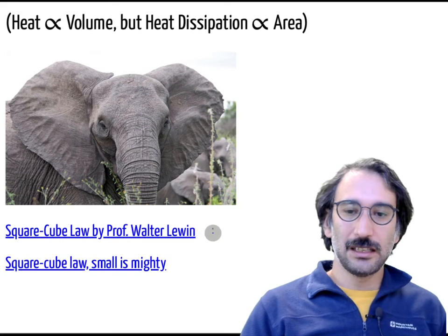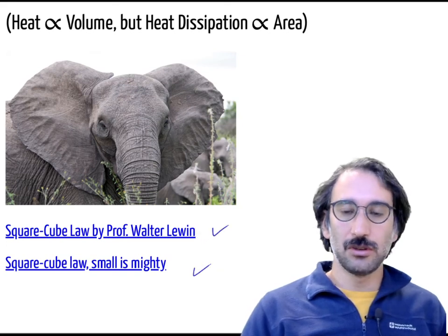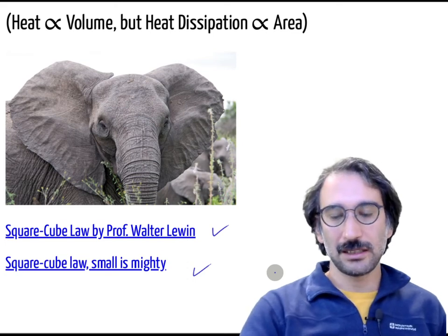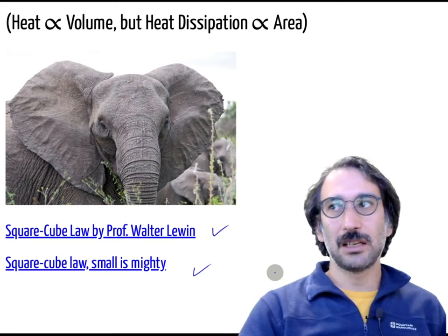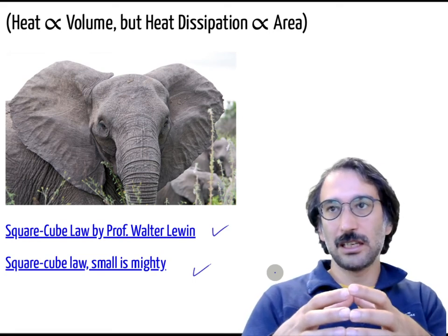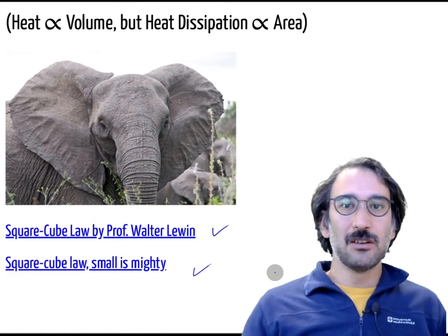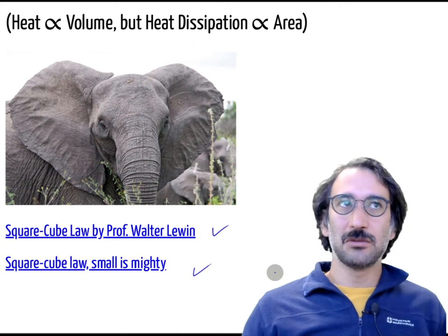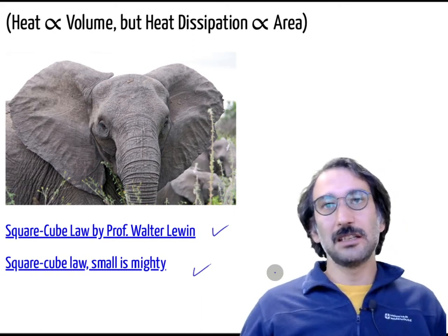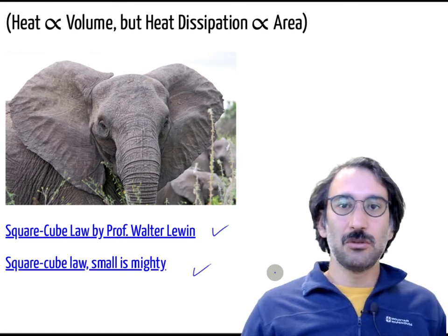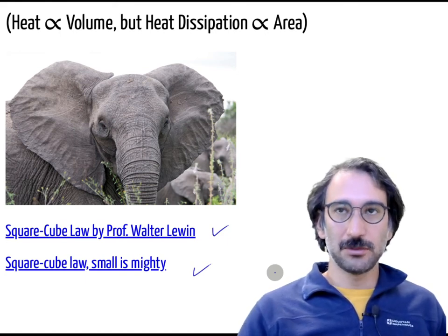Again, have a look at those original videos and reading materials, and we have exactly the same relation for power electronics. It can be easy to cool down a circuit at a smaller scale. Let's say if you are designing something for a few kilowatts, it can be easy to dissipate because you have lots of surface area. But if you are designing something at the megawatt scale or 100 kilowatts scale, then cooling may be a more difficult problem. So that is why you need to be careful about those applications.